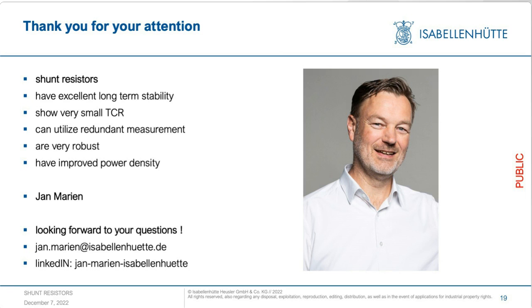And in addition, these full metal shunts are very reliable because there's no organic material included in the design. And finally, these are very good for the pulse rating, as the metal of this shunt has a very high heat capacity.